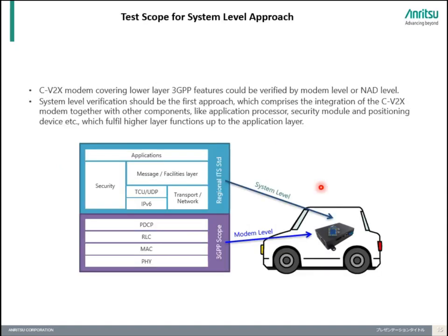So you have seen this diagram when Sahu was presenting, right? Typically there are multiple ways you can go about testing your CV2X product or module. One, you have your physical layer verification or validation, right? For which you would need an RF call box or an RF measurement analyzer.